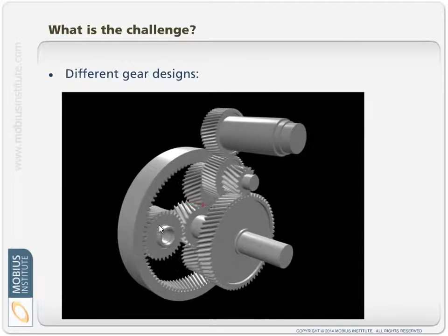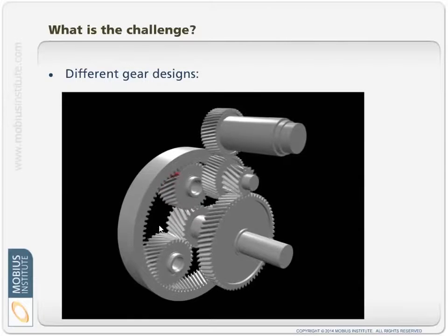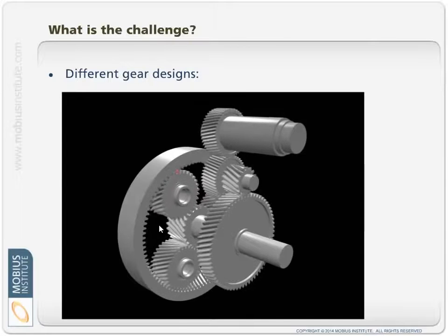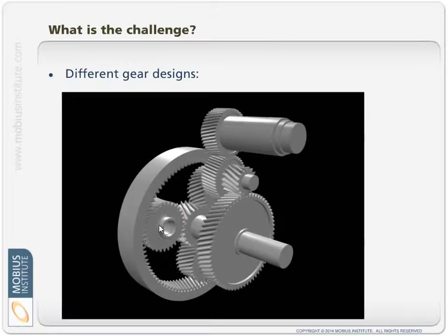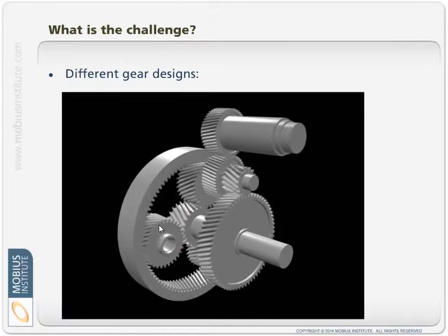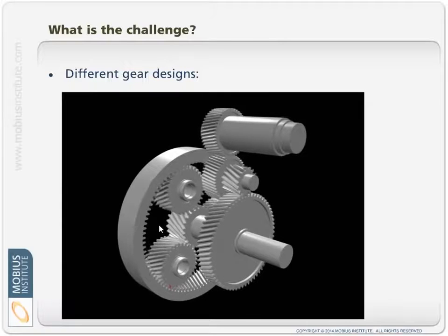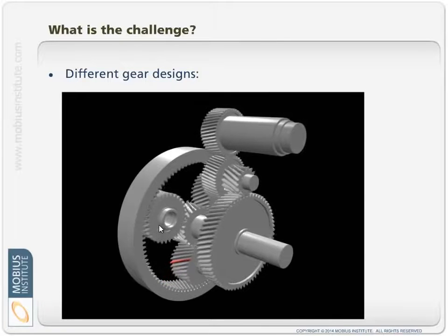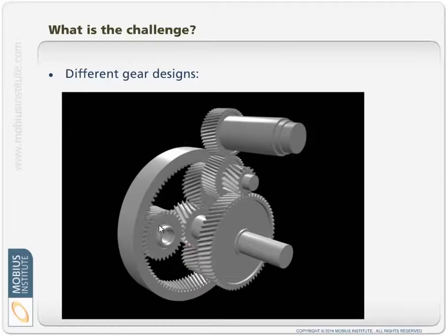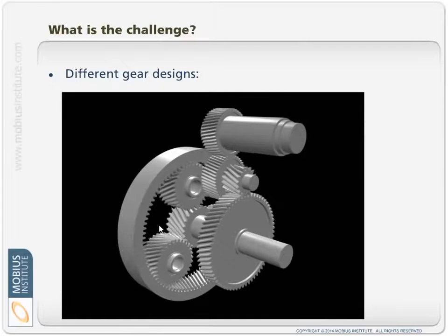If you think about this gear here, it's now moving away from my accelerometer, and it's going to move back towards my accelerometer. You've got to think about the different failure modes, and that's certainly something that will help you with vibration analysis with your particular gearboxes, is to consider what the failure modes have been in the past if you've got a long history with the machine. So at least you can make sure that you can detect those fault conditions. As with everything in vibration analysis, sometimes you have to make compromises.